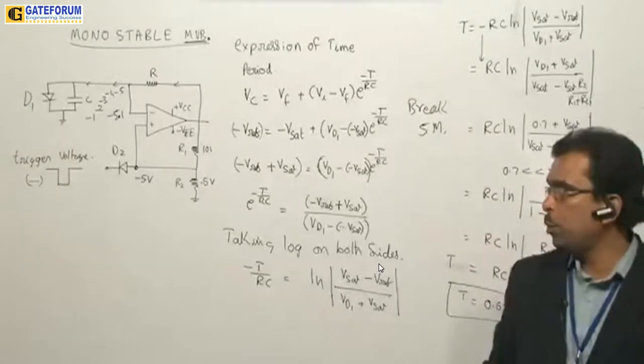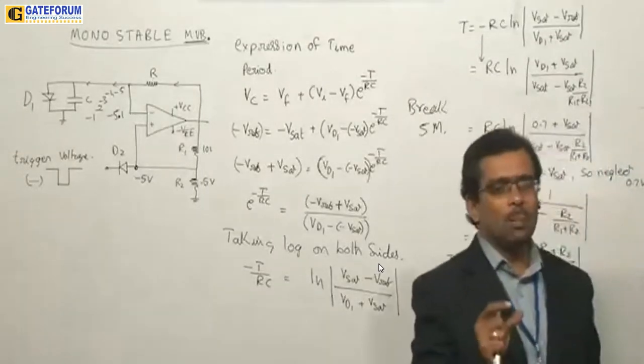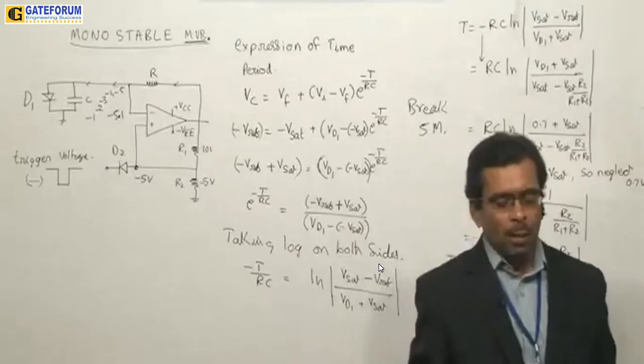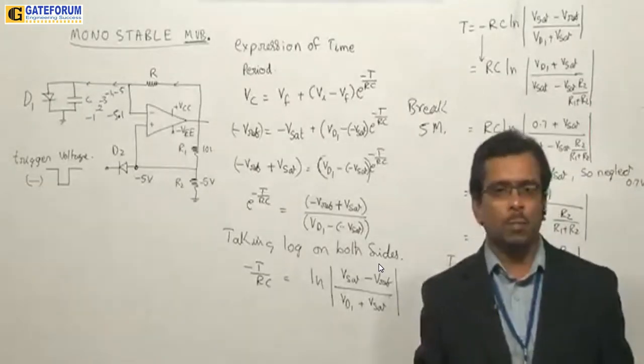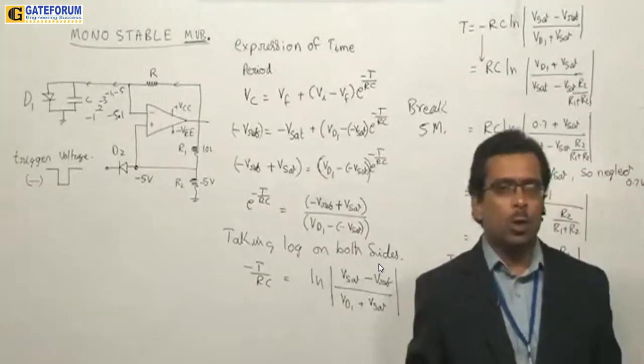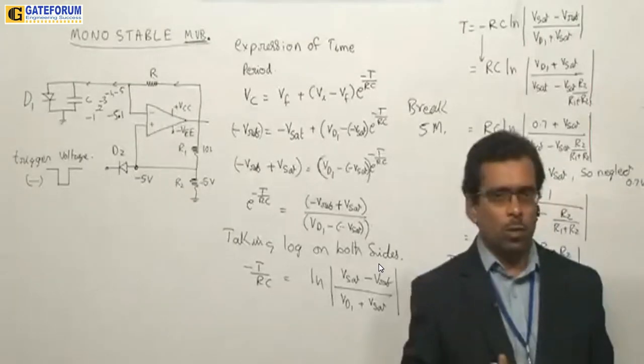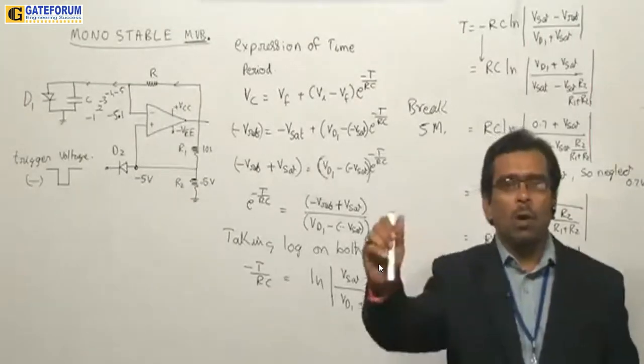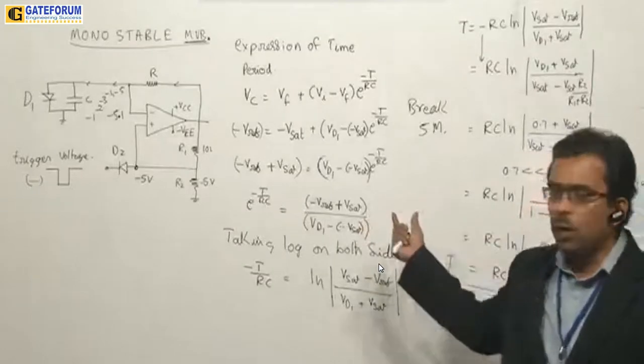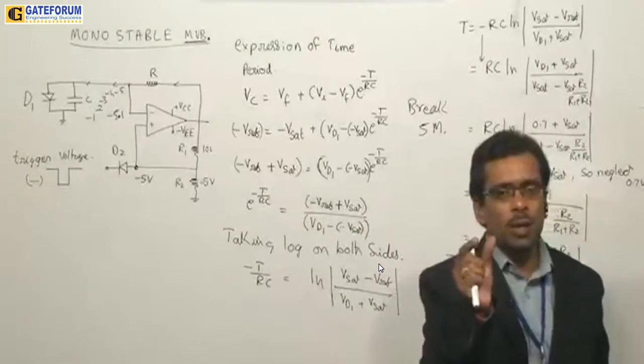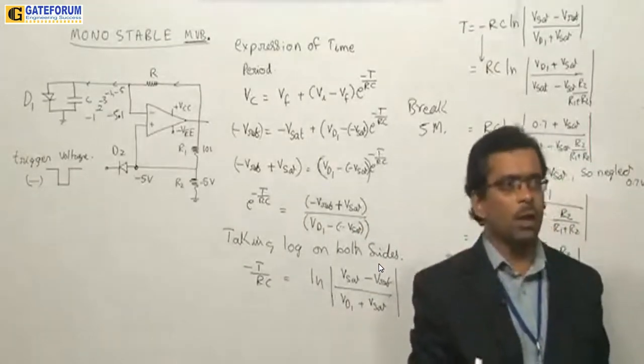Right. So if you try to put the capacitor at a very low value, what happens is it will get saturated very quickly. So it will stick to 0.7 volts. Okay, that is the point. Then the output pulse that you are getting, that pulse time period will be decreased. That is what is going to happen.